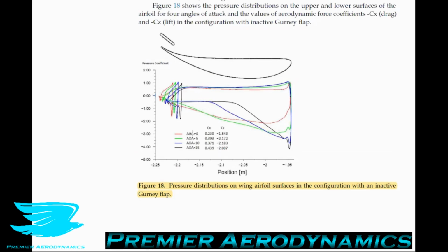What does this mean? Well, when we have the splitter, like the spoiler, at 0 degree angle of attack, the lift and drag that we get are a certain value. We increase the angle of attack by only 5 degrees. The drag increases pretty badly, like a 30% increase. The lift only increases by about 15%. So we're getting a massive drag penalty for how much downforce we are producing. Is that a bad thing? Not necessarily, depending on what we want to do with the car.